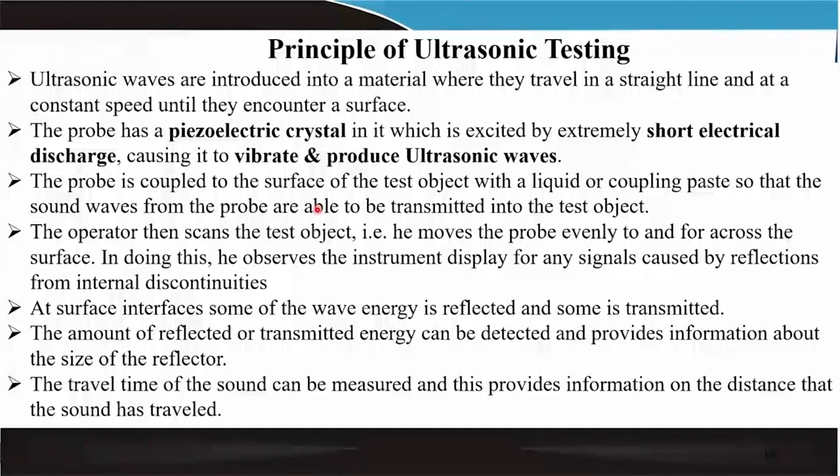If your thickness is known and you know what the depth of penetration of the sound should be, then if there are any defects you can always compare with a standard specimen or standard component, and find the location of the defects from the discontinuities in the ultrasound wave.